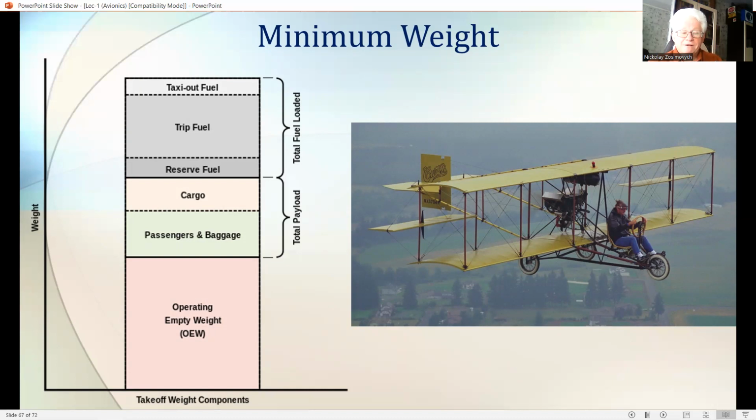An increase in engine thrust is therefore required to counter the increase in drag, and the fuel consumption is thus increased. Do you agree with me? Nice. For the same range, it is thus necessary to carry more fuel, and the payload has to be correspondingly reduced.